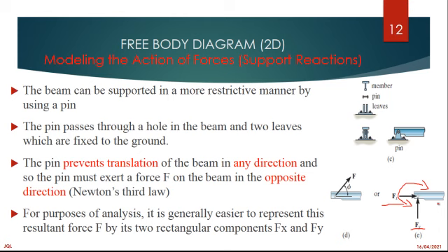So the only reaction that we have on a pin support is just those two members. The member itself in the X and the other member in the Y. This is also the same as representing it depending at which angle it is being applied. Can you remember about the components of a force? You have a force at an angle, then you find the components in the X and in the Y. This is exactly what is happening.